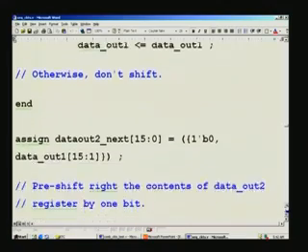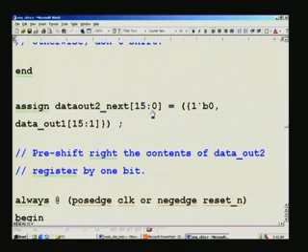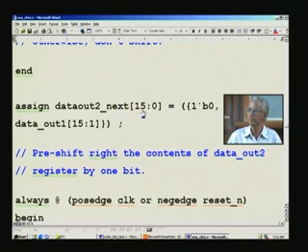It is exactly the same except that the assign statement is slightly different. What is our goal? It is to right shift by 1 bit. So we can take those bits 15 to 0; if you right shift, what will happen? Bit 0 will get lost, so what remains is 15:1. So we just concatenate two numbers, that is 0 on the MSB, because the vacated bit will always be 0. That is the nomenclature adopted earlier for that arrow that you have seen there.